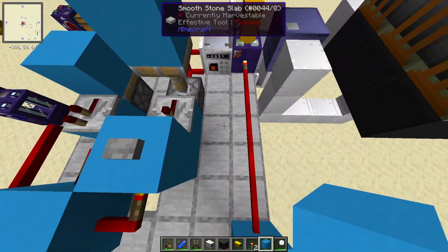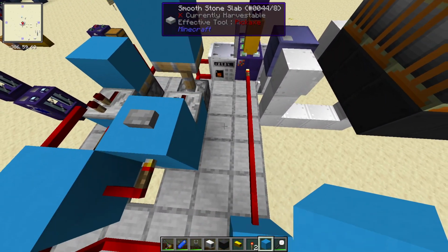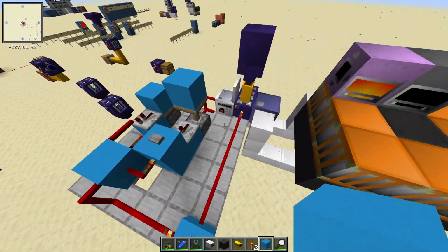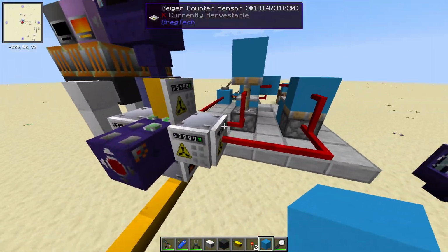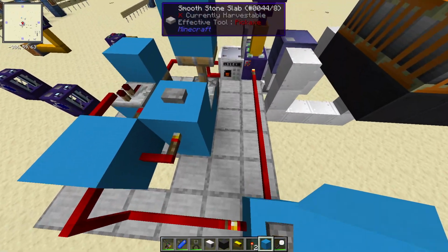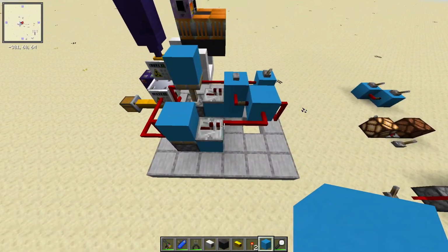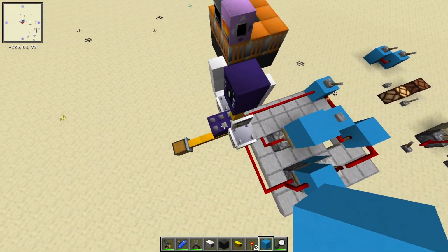But like I said, I prefer when there's an extra additional input required to fully turn the reactor back on, because I find that when I'm doing maintenance on the reactor, I just want to double check everything before I fully turn it on, and it kind of requires you to think twice. But it's really up to you. This is essentially just the most stable and simple way that you can have this kind of control circuit.